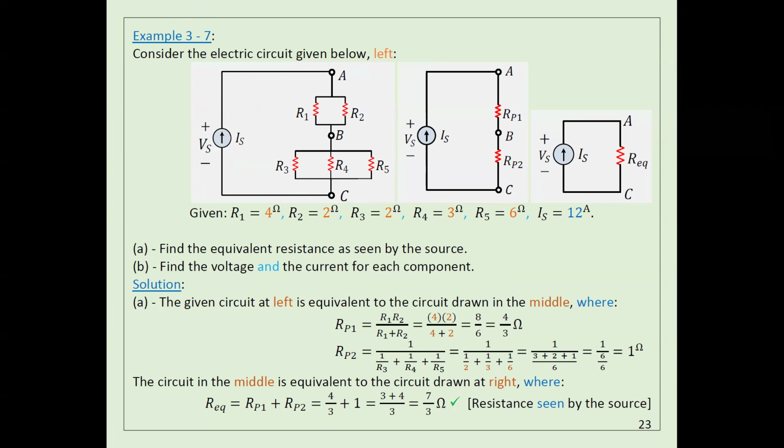The most difficult part, in my opinion, is that you need to know which resistors are in parallel and which are in series. That's the most important thing. As you see here, this current is going to come this way, and then this current is going to split between these two resistors, and then it's going to be collected here. So this current IS is here. If you add I1 plus I2, it gives you IS, because it splits and then adds together here.